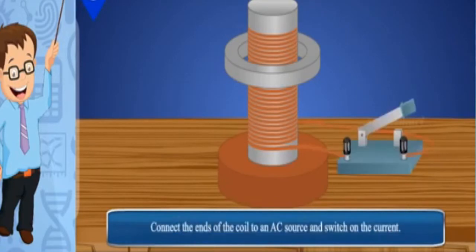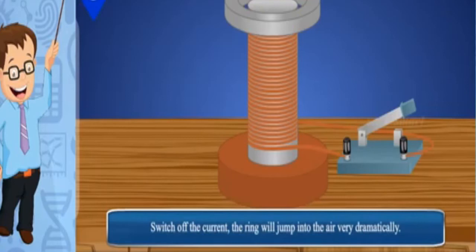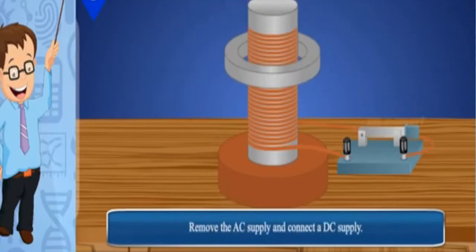Connect the ends of the coil to an AC source and switch on the current. The ring is elevated, that is, raised in the air. On switching off the current, the ring will jump into the air very dramatically. Remove the AC supply and connect a DC supply. Observe what happens. Could the ring be elevated if DC is used?